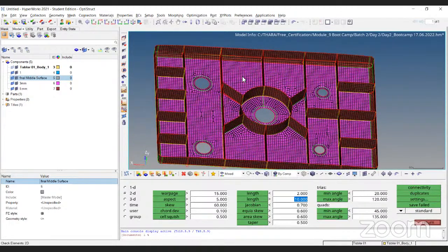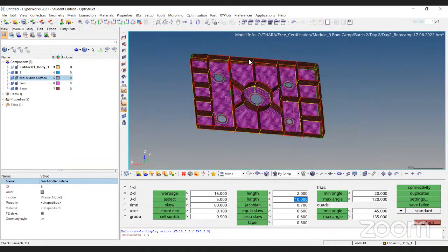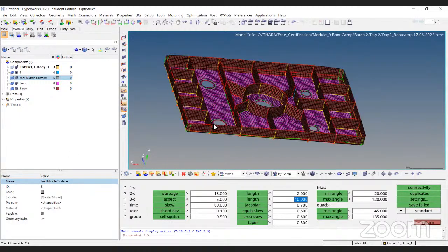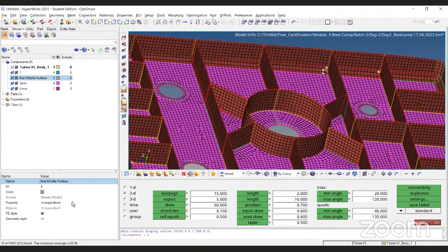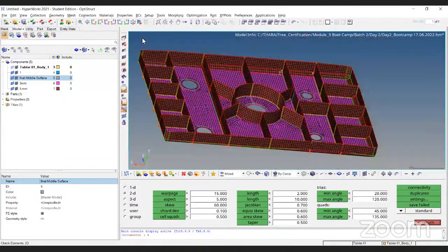And all my elements, no matter how many elements or components there are, should be within this range only. We'll see how to clear them one by one. You just click on this component. Observe in the status bar, there are 10 elements failing. Here it will show 15,667 elements, which is the element count. This complete component has around 15,000 elements, and now 10 elements are failing.